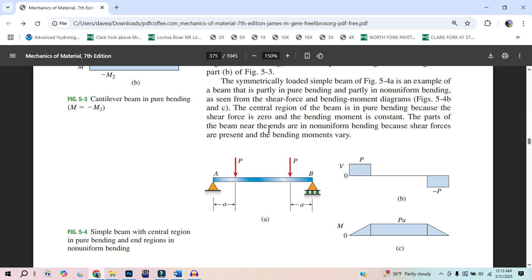If these are trying to rotate things this way, these two loads could be replaced by just a P right here at that distance. They could be replaced by one of these loads just right there. I think that's surprising, because it shows you that this one's really not generating much moment. We're not taking both of these loads and putting it there, hell no. But we're saying both of these are causing a torque, a moment, you know what I mean?